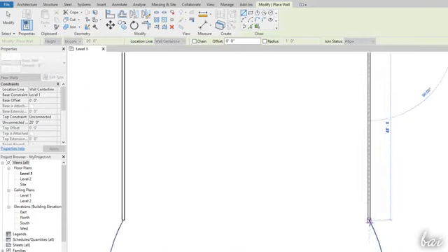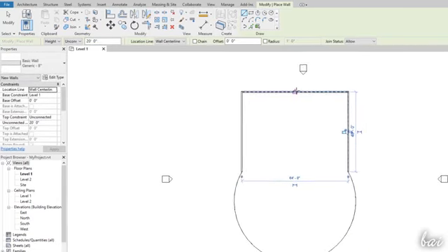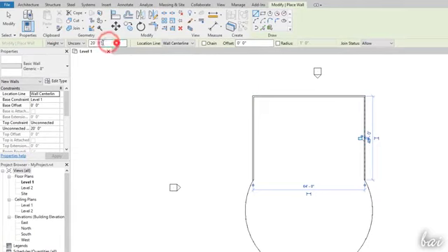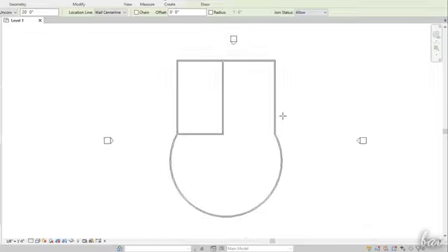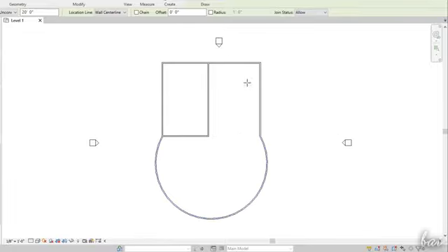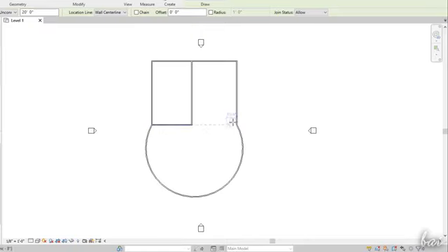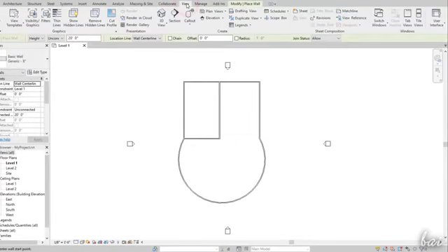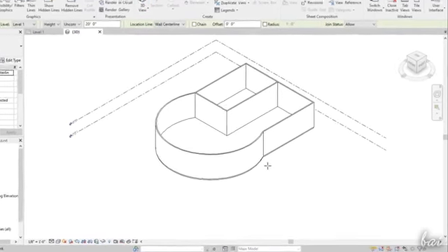The walls are made with their base on the ground plane, spreading in height as it is defined in the top left corner. In this preview, you won't be able to see any height on the walls. By default, this preview uses a 2D view from top to bottom called Level 1, as you can see from the tab on top. To check your walls in a full 3D view, you can create one by going to the View tab and then to 3D View.